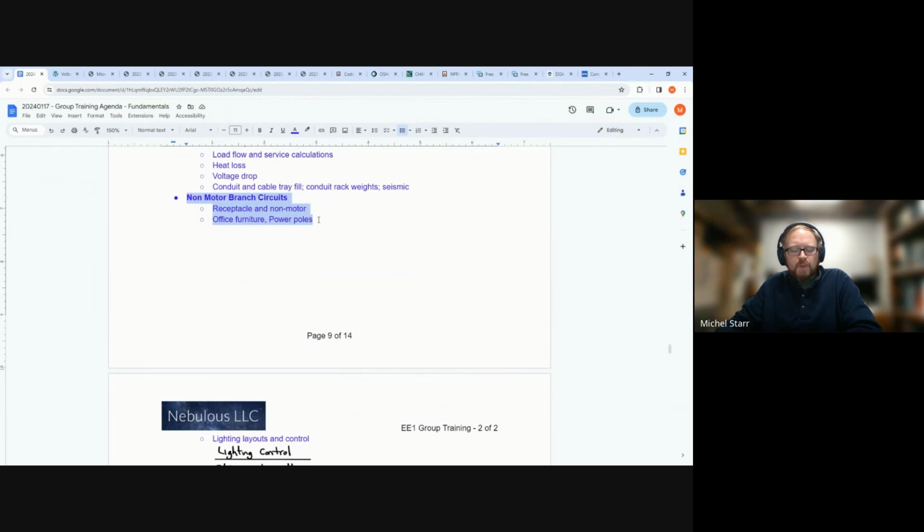I didn't say one reason why the code would allow you, for motor loads, to set the breaker higher. We know the transformer and the motor will have higher current at the start, so we're just going to set the circuit breaker higher. That sounds reasonable, then it won't trip. But then what about when it's operating normally? We want it to trip then too.